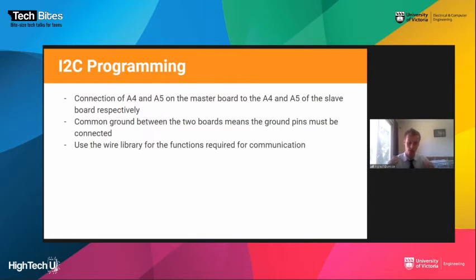And while we can have this work without the pull-up resistors, what that leaves it in is kind of like a gray area where we don't really know what the value at that pin is. And so by putting a pull-up resistor, we're basically saying it is high until we pull it low.